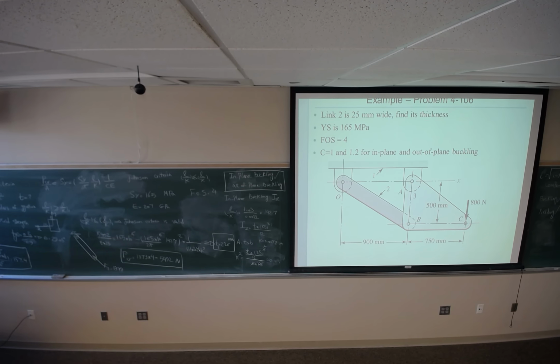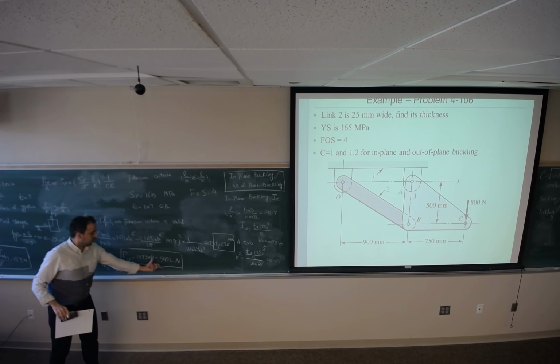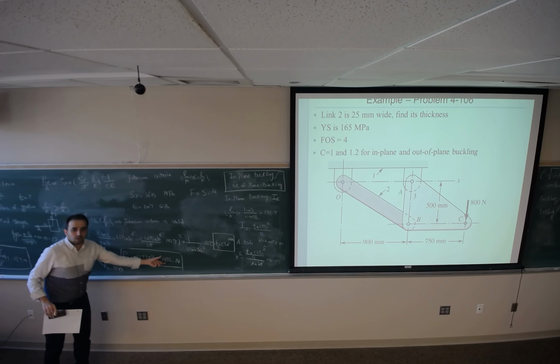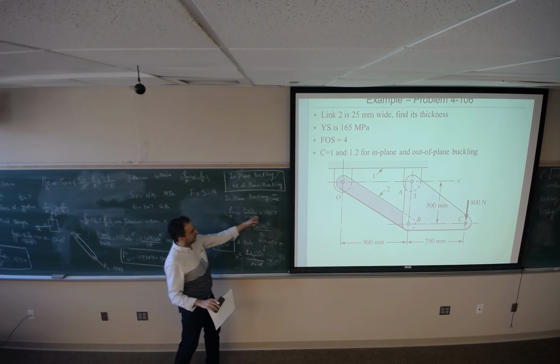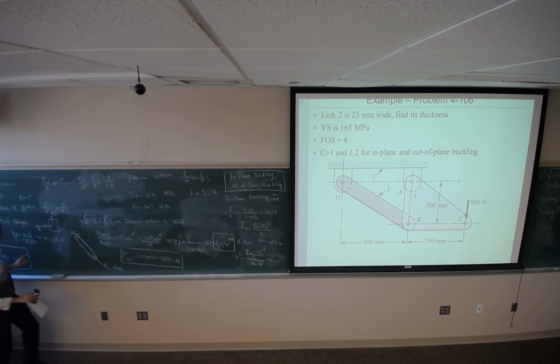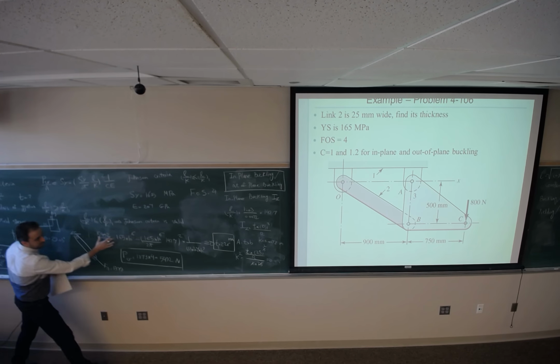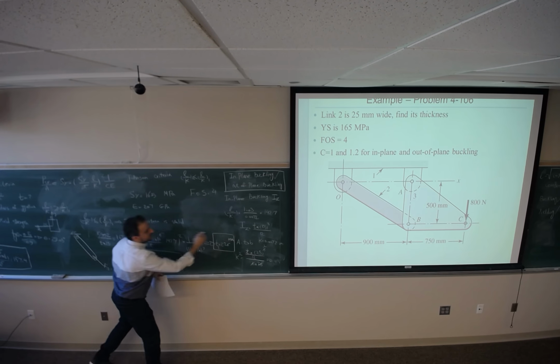Any question on this? Does everybody know why I multiplied this by 4? The force that I calculated. Then I found L over K1, I calculated L over K, compared them, and concluded that we should use the Johnson criteria, plugged in the numbers, and found the thickness.